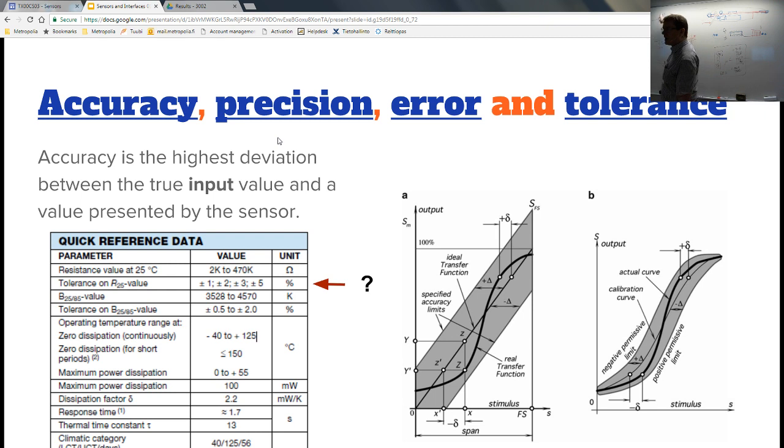So most of them actually are on that one, but this is a statistical measure. So in 1,000 pieces, you probably have 1 or 2 that are not fitting this 2% range. 6 sigma is about 0.001, so it's 1 over 1,000, I think. Sigma is here just the standard deviation of the curve. Okay, so that's how the manufacturers are actually using it in their tolerance presentations.